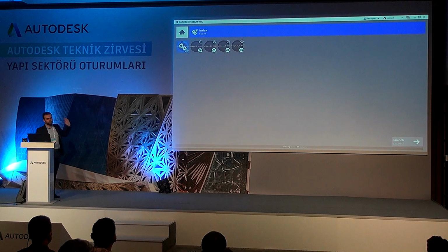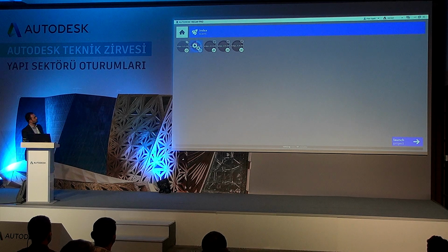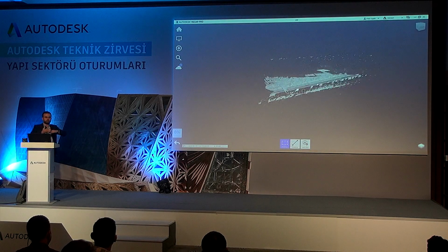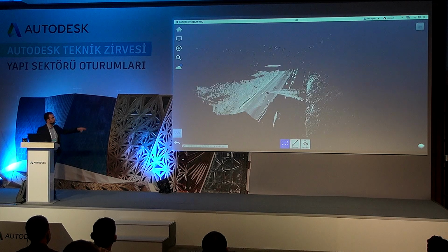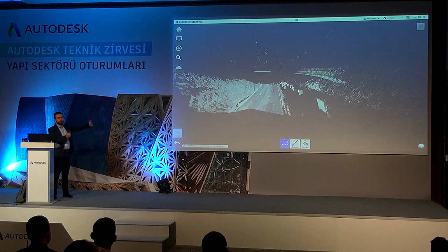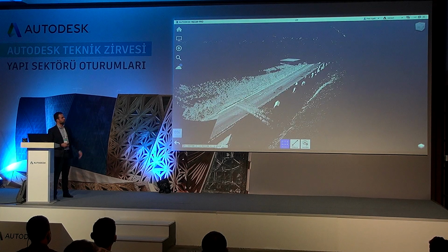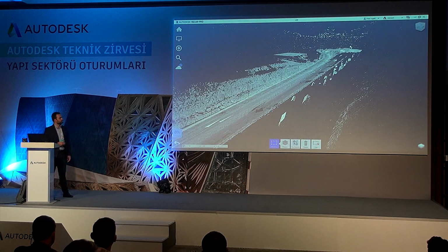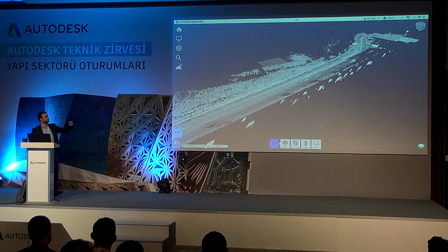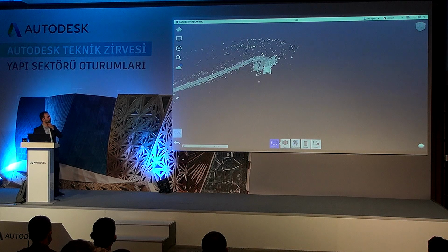And we'll do the translation for all of the billion points. Not only that, it will also take into account the different scans done at different intervals, and we'll put all this data together, which we call stitching. So it will stitch data together to get what we have in that model. Definitely this is just one sample, one stretch of the road. But as you can see, we have a lot more details than just by the normal way of picking certain points.